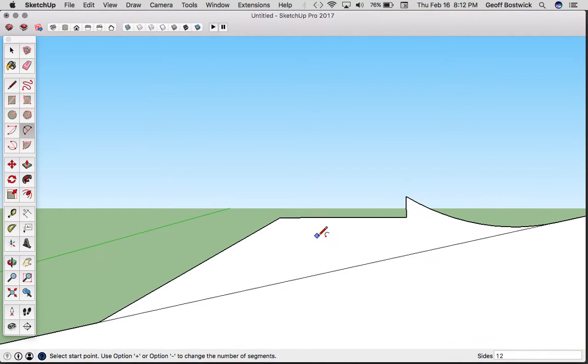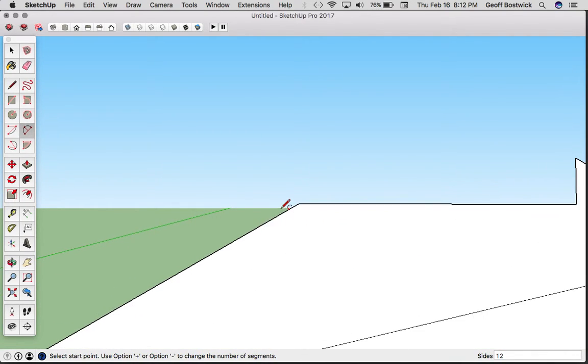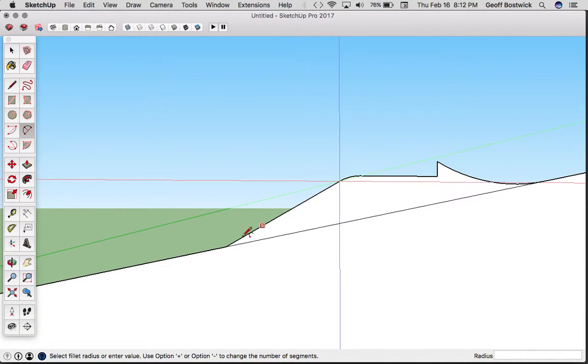We want to do a couple things to make it a little more fancy. Round off the knuckle. And you'll notice if you click once somewhere along there, and you slowly move along this, it'll turn pink, which means it's lined up at both edges. So I move along here. And if I double click, it automatically gets rid of the extra excess.